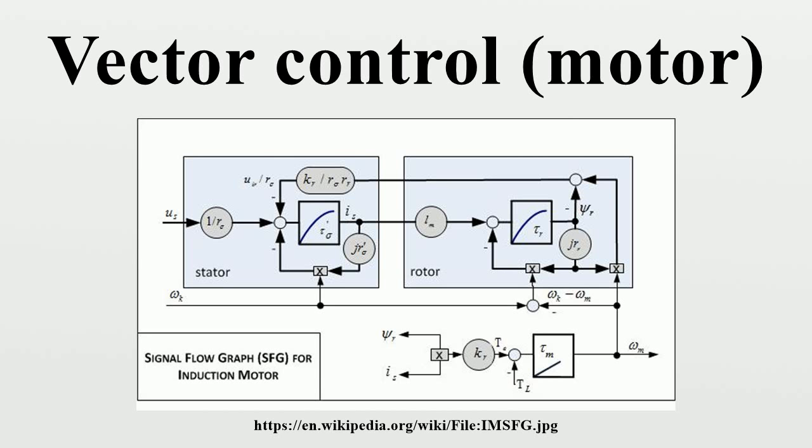Inverters can be implemented as either open-loop sensorless or closed-loop FOC. The key limitation of open-loop operation is the minimum speed possible at 100% torque, namely about 0.8 Hz, compared to standstill for closed-loop operation. There are two vector control methods, direct or feedback vector control and indirect or feed-forward vector control, IFOC being more commonly used because in closed-loop mode such drives more easily operate throughout the speed range from zero speed to high speed, field weakening.